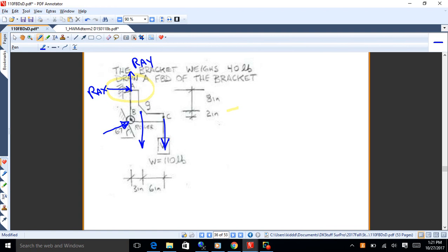A roller like that couldn't produce a force in the other direction. That's true. A roller, as shown, could not produce a down-left force. But sometimes with the difficulty of drawing, you can assume that even though it's drawn as a one-way roller, it acts like a two-way roller, because it's so hard to draw something like this. This is like a schematic symbol. But yeah, in this case, you're right. I think that force will push up.